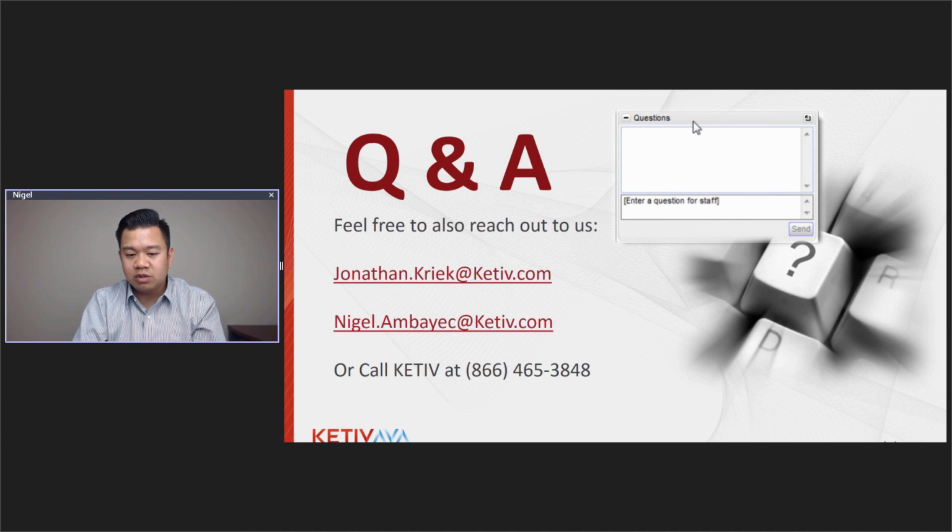Definitely. And then this is a question that I was going to ask too, or I figured that people would want to ask, came from David as well. How do you update the model changes? When you update the model in your Inventor, what happens to the people on the browser? So what happens is you're actually publishing a viewable. Because of the IP concerns a lot of our customers had, we're actually converting the Inventor CAD 3D data to a visual file form and then sending that up to A360. So you're not actually sending any of your IP from a CAD perspective to A360 with this workflow today. And so because of that, it's a snapshot of that model in time. So if you do model updates, you have to do another publish so they can see that the changes have been made. So you can see the history of visualizations that are created based on model changes. I hope that answers the question.